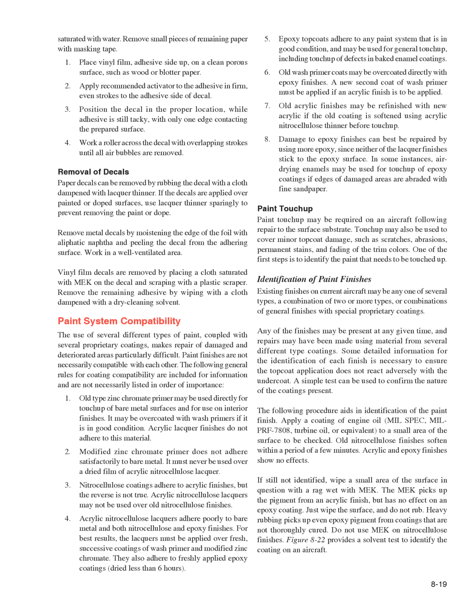4. Acrylic nitrocellulose lacquers adhere poorly to bare metal in both nitrocellulose and epoxy finishes. For best results, the lacquers must be applied over fresh, successive coatings of wash primer and modified zinc chromate. They also adhere to freshly applied epoxy coatings, dried less than 6 hours. 5. Epoxy top coats adhere to any paint system that is in good condition, and may be used for general touch-up, including touch-up of defects in baked enamel coatings.